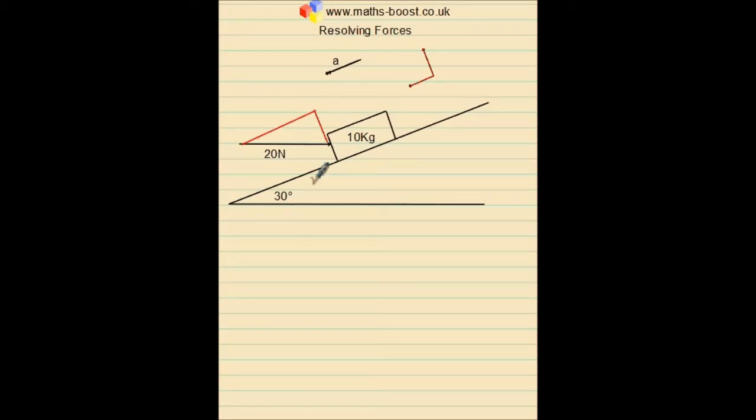And don't forget to consider the direction of the forces. So our resultant force is starting here and finishing here. So to make the same journey, we'll go in this direction and then down. Once again, we have a right-angled triangle due to the fact our chosen directions are perpendicular. And in this case, it's easy to see the corresponding angle is going to be 30 degrees.